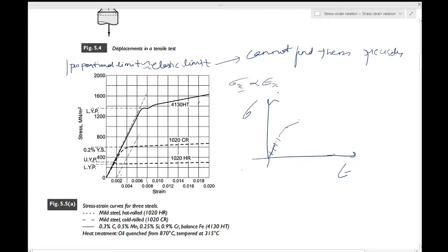Eventually you find that you have reached a value after which, if you unload the material, and you have to keep taking a new material each time, you will get back to a point which is not zero strain. You come back over here. So this is also a limiting case. How is it a limiting case? Because the idea is that the point which you considered just before this, if you unload from that point, it should come back to 0.